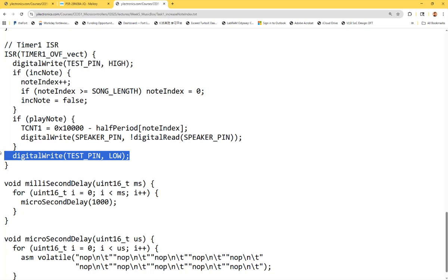The period, yeah. So if you use a cursor, right, bring up two cursors, that pulse could be really narrow or really wide. So that's going to be really important information as well. So you'll know how long the ISR takes to finish. Okay?